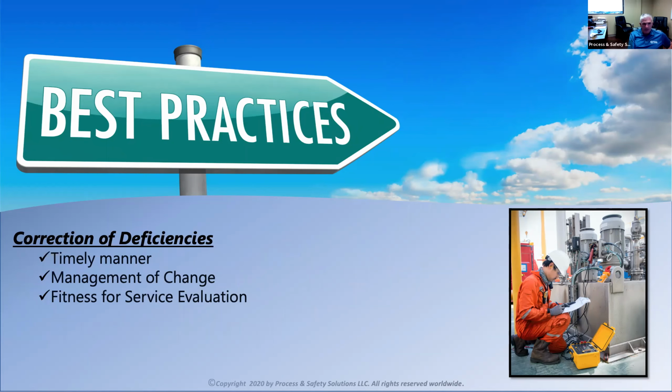So if you have a vessel where the UT thickness shows that it's less than the designed thickness amount, no matter how much that is, you must do a fitness for service evaluation on that. Either re-rate the vessel or go through another process to determine fitness for service for that device, especially if it's already outside its corrosion allowance. Same way with piping, that must be done as well.